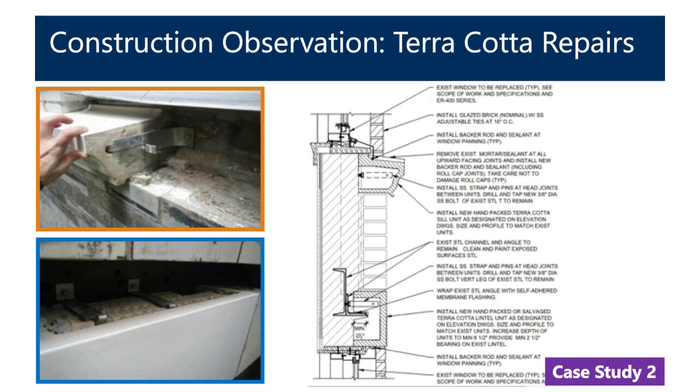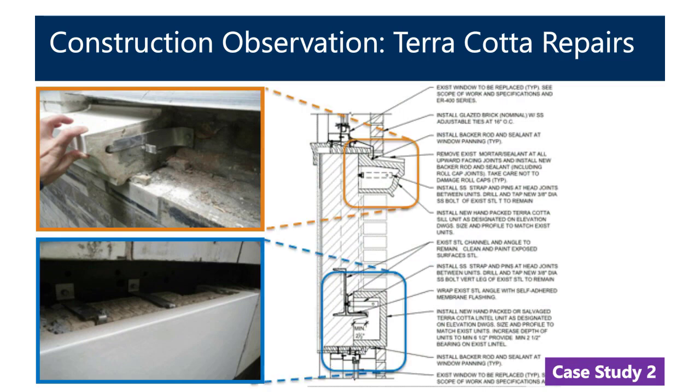And as you'll note, the anchors that are shown on the drawings are not exactly the anchors that are shown in the scope documents, but that's exactly what was intended, that there is an intent for anchorage, and a lot of these things oftentimes have to be reacted to and changed in the field. While it's relatively simple here, there are other instances where things need to adjust for the actual field conditions.